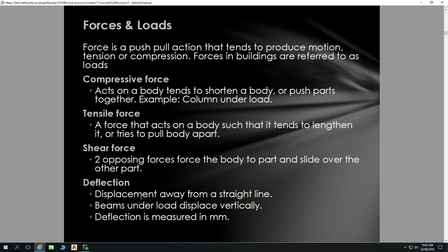So we want to minimise that deflection, or accept that some deflection is going to happen, understand the extent to which it will happen, and accommodate that with the right amount of gap so we don't get glass breaking, or by enclosing the elements that take that deflection so we don't see it in a visual sense.